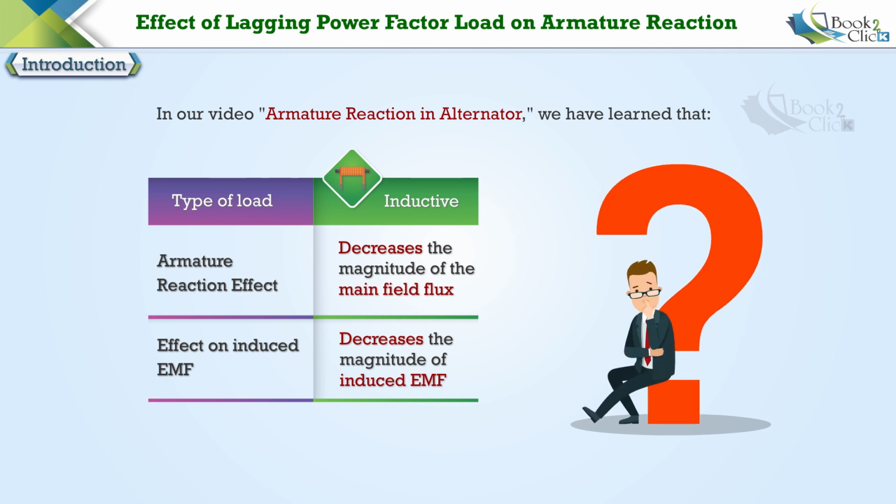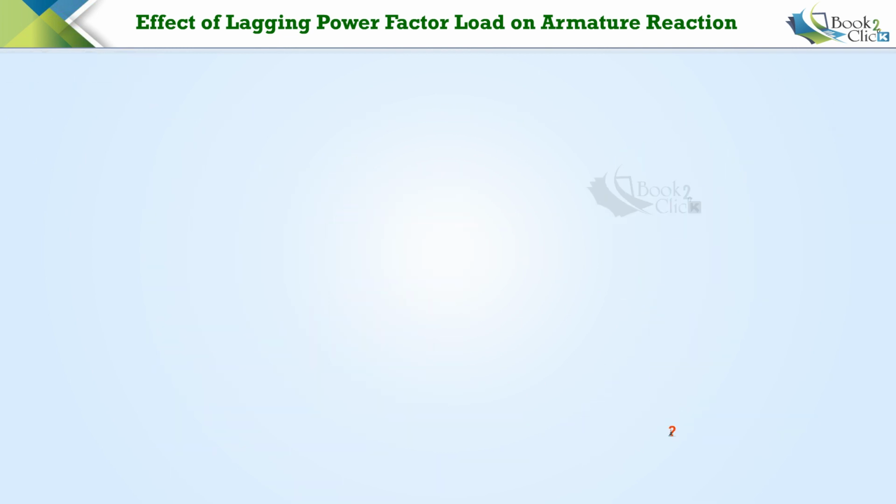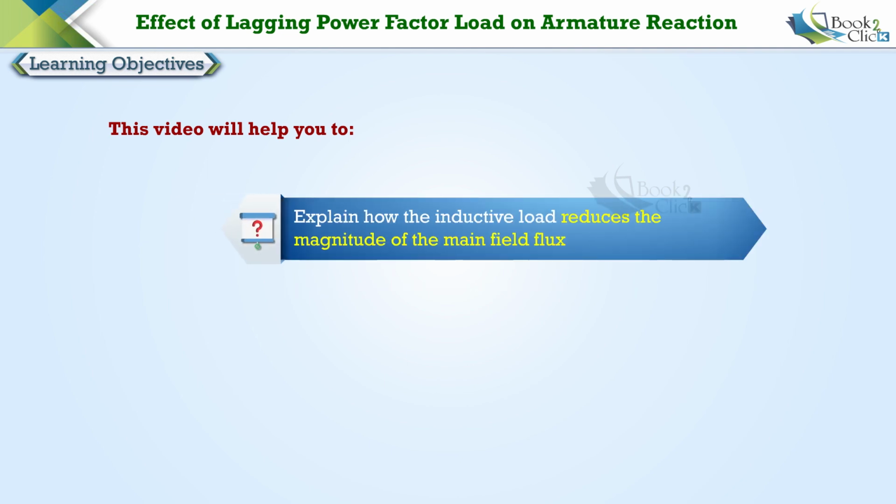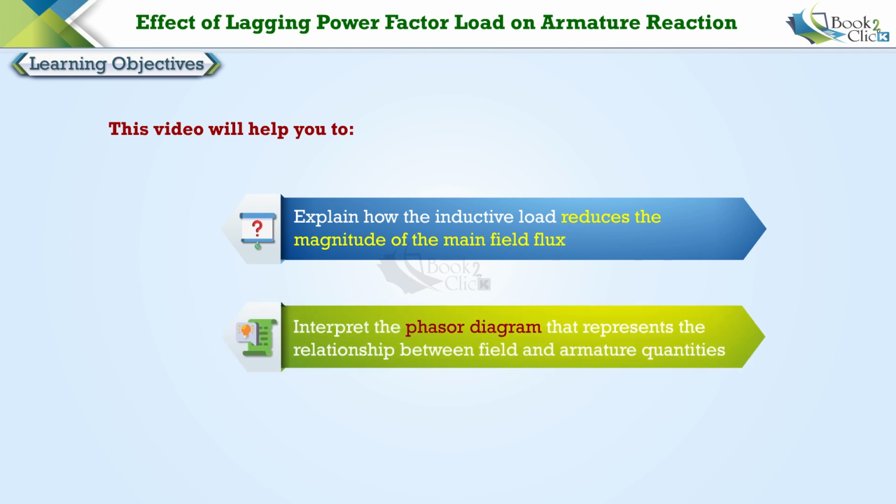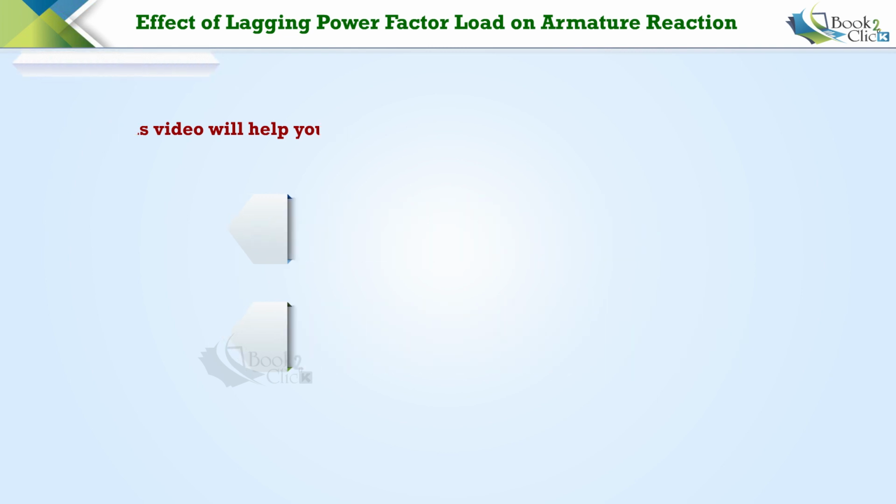Are you curious to know why it happens? This video will help you to explain how the inductive load reduces the magnitude of the main field flux. Interpret the phasor diagram that represents the relationship between field and armature quantities under lagging power factor load.